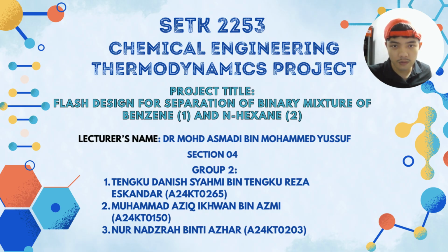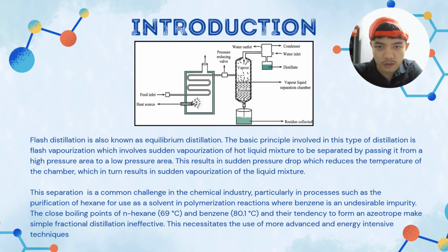We from group 2 present our project with the title Flash Design for Separation of Binary Mixture of Benzene (1) and n-Hexane (2). Flash distillation is also known as equilibrium distillation. The basic principle involved in this type of distillation is flash vaporization, which involves sudden vaporization of a hot liquid mixture to be separated by passing it from a high pressure area to a low pressure area. This results in a sudden pressure drop, which reduces the temperature of the chamber, which in turn results in sudden vaporization